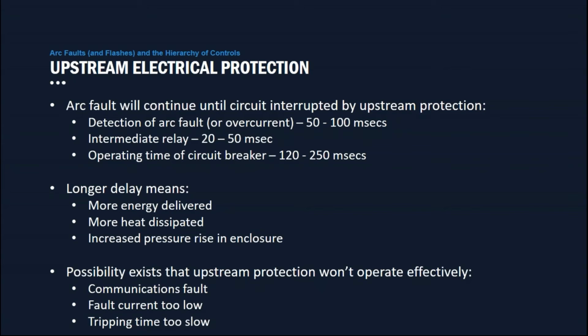duration of the fault. So sometimes people make the mistake of saying, oh, we can detect a fault within 50 milliseconds or 100 milliseconds. Well, that's only half the story. Detecting the fault is not sufficient to clear the fault. Obviously, you have to operate the breaker. So the longer delay, more energy delivered, more heat dissipated, and increased pressure rise.